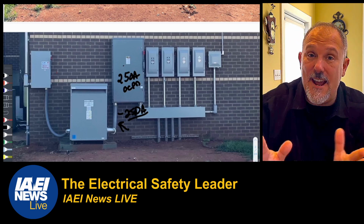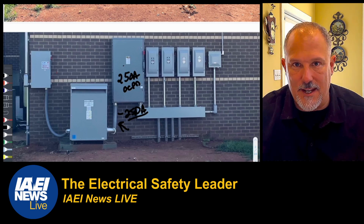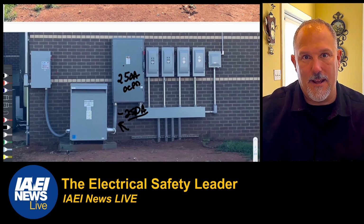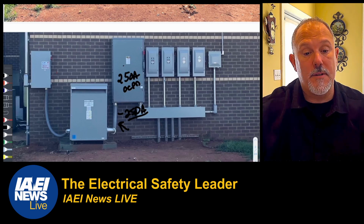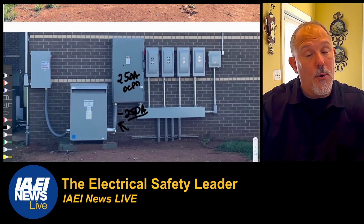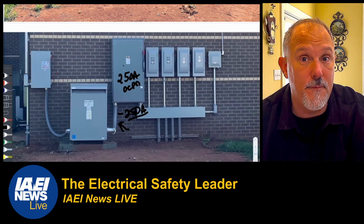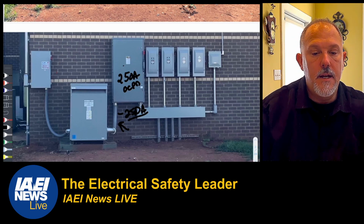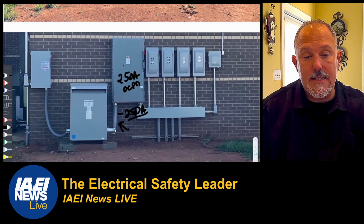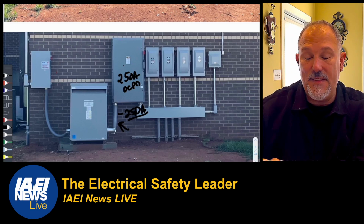So if you didn't have that language, and if that was a 400 amp fusible disconnect and you put 300 amp fuses in, then that conductor size would have to be 400 amps. But because you have the "or not less than the rating of the overcurrent protective device," which in this case could be a 250 amp fuse, then I can use 250 amps worth of conductor, and that 250 amp fuse could be in a 400 amp fusible disconnect. So there is an exception where listed equipment such as surge protective devices, so they give you the exception for having a surge protective device in that application.